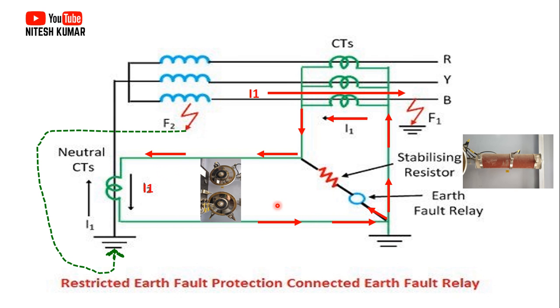So to protect that, we have connected one non-linear resistor in parallel with your circuit, which will surge that voltage, and this will allow only the permissible voltage as per the setting to the relay coil and the circuit. This is also called the voltage dependent resistor, and also the non-linear surge arrestor.